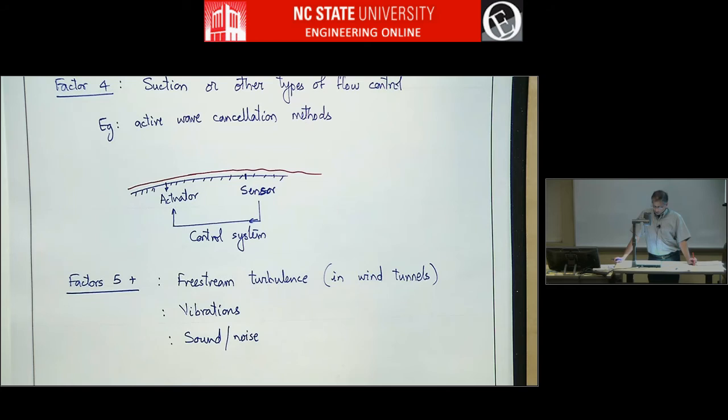So if you put a model of an airfoil in some wind tunnel, you get the drag and lift at some angle of attack. And then you take the same model and go to some other wind tunnel, you get fairly different answers. And it bothered people for a long time until they realized that wind tunnels have free stream turbulence, right?